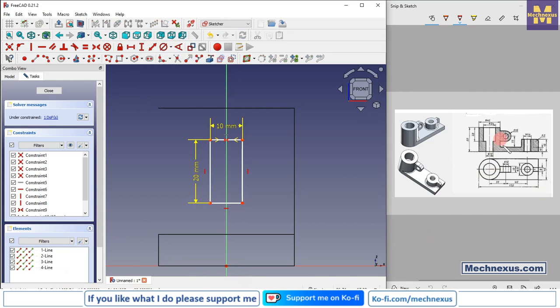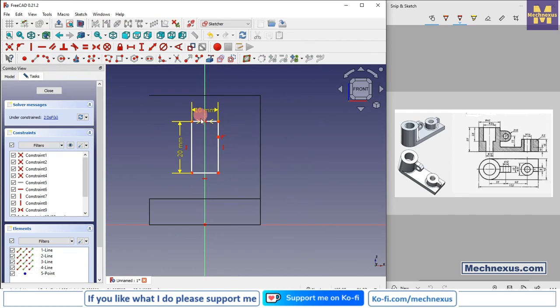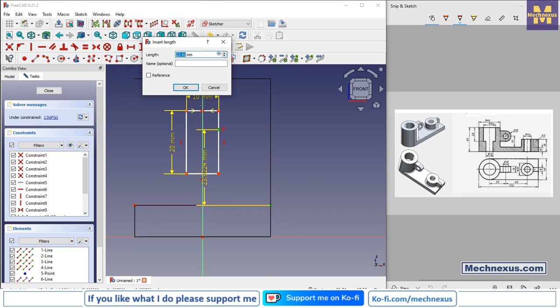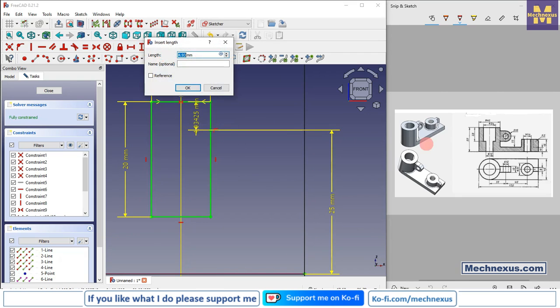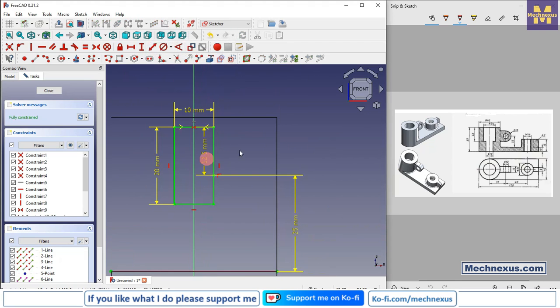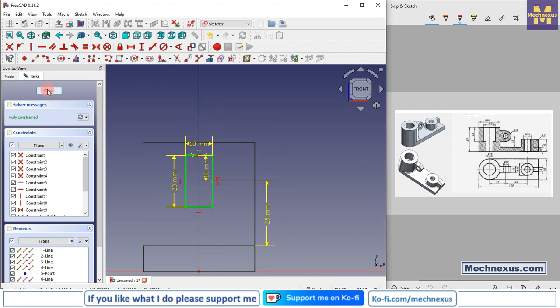And now here is a position of 25 mm, so we will create a point and make this point coincident, and we will create a dimension. We will project the edge and select this and provide a vertical dimension of 25 mm, and from this to this the vertical dimension will be 12.5. Sorry, it is in the center, so it is 20, so it will become 10, so that it will be in the center.